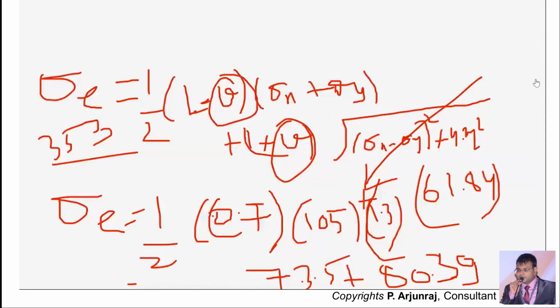to the proportional increase in the length in a sample of the material which has been elastically stretched. So you can also tell, it is the ratio between the lateral strain to that of the longitudinal strain. With respect to the material point of view, when you're taking the solid mechanics or the material aspects, this Poisson ratio is going to relate to the deformation of the material in the direction which is perpendicular to the load.